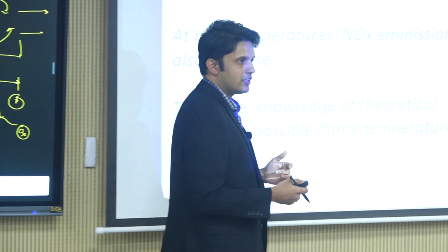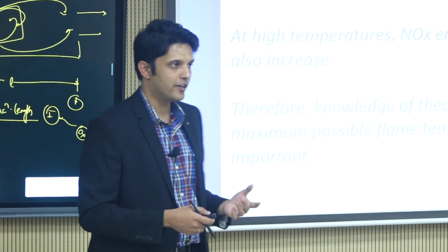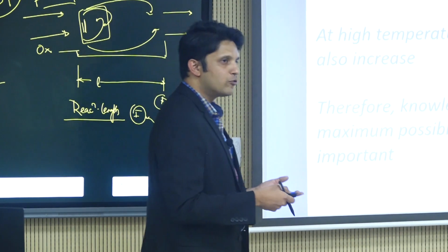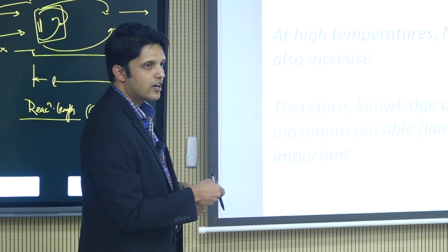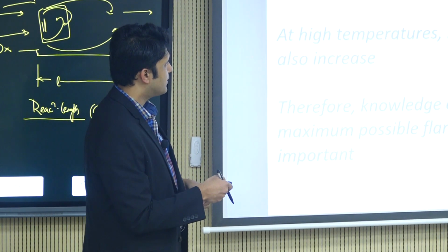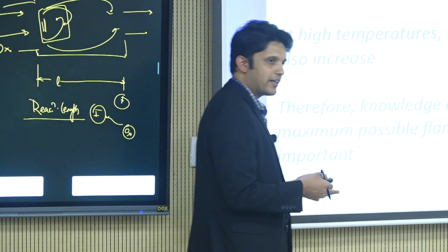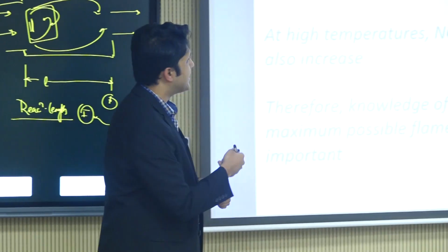Okay. Now, even if these values are correct, the integrity of these metallic components, they will start yielding at those temperatures if you run it for a long time, right? So it can have thermal stresses developed, and it will lead to failure. So it hampers the durability of these kind of reactors. That is one of the reasons why you need to know what kind of temperatures you are going to expect at the flame front, so that you can employ effective heat management.